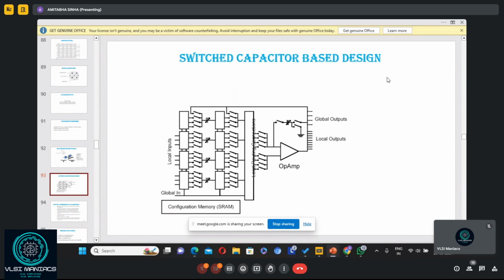So when we write the program in a mixed signal processing language, typically a high level one, written in VHDL-AMS or Verilog-AMS, then after compiling, we do the synthesis, and then the bit stream after testing and verification is downloaded onto the configuration memory.